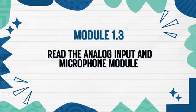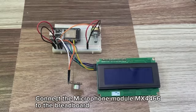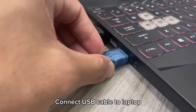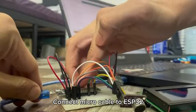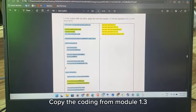For module 1.3, read the analog input and microphone module. We can maintain the connection and add this microphone module following this connection diagram. Connect USB cable to laptop and connect microphone cable to ESP32. Copy the coding from module 1.3 and update the coding into Arduino. We compile the coding and upload coding into ESP32.